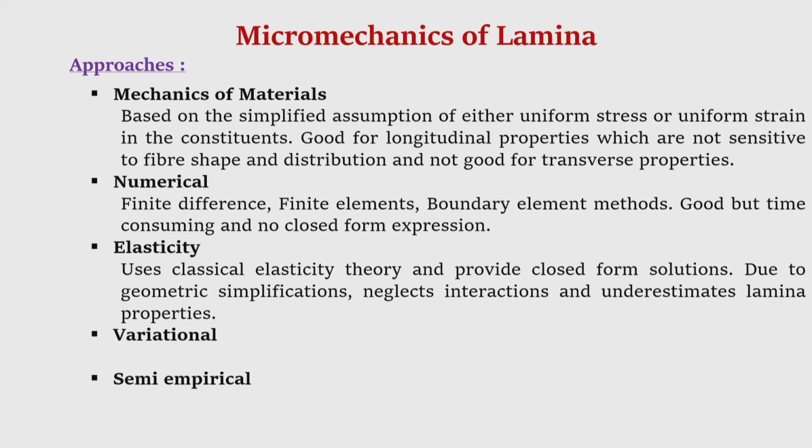Okay. Then elasticity methods or approaches are based on the classical theory of elasticity, where the equations of equilibrium, compatibility conditions and the boundary conditions are used to arrive at a closed form solution. However, simplified assumptions are made in terms of geometry, and therefore, sometimes important interactions between the fibers and the matrix are not considered, and they do not agree well with the experimentally measured values.